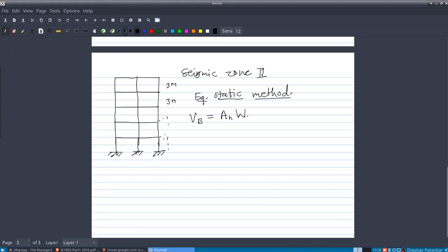So that will give you the dead weight or dead load, and then imposed load will be given on each floor. Like let us say here on the first floor, it is 2 kilonewton per meter square. I'm just getting some numbers here. Let us say it is 3.5 kilonewton per meter square, and so on. So if I am considering imposed load for W1, that is the first story, what imposed load should I take?